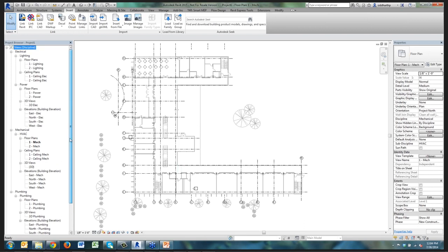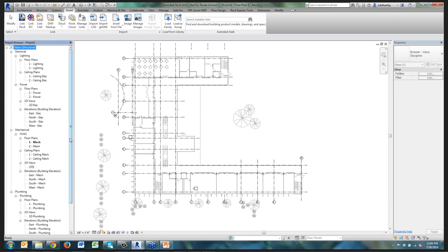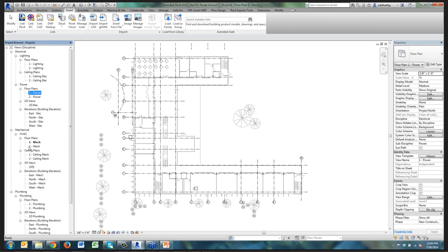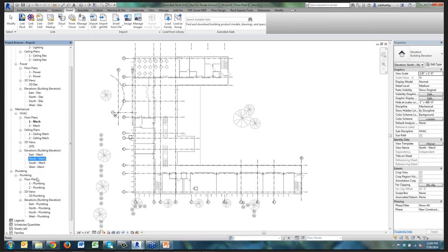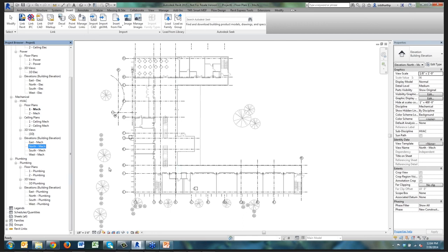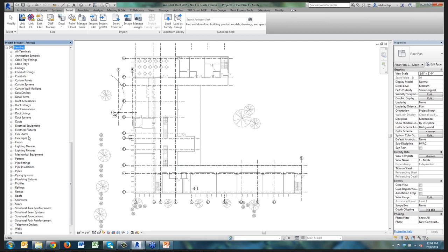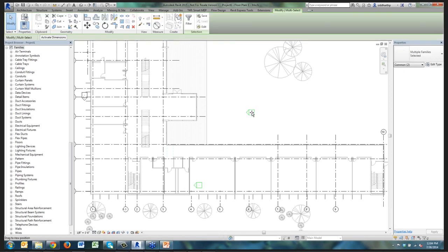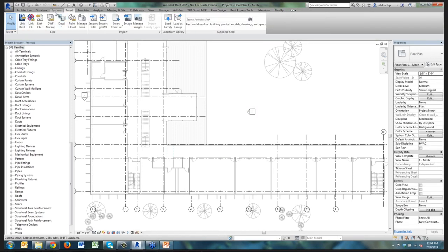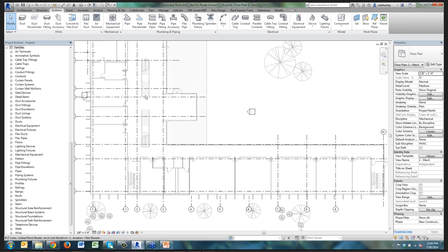template. So the systems template, if you're familiar with the out-of-the-box template, has got views predefined for the different electrical levels. So you've got lighting and power views, and it has a mechanical view available and also a plumbing set of views available in it. What you'll also see in this template are some families that are preloaded, and we would be using some of these families and then getting into the connector definitions for these families to see how the flow works together within these families. So to begin with, what we'll do is we'll start with this linked model here.